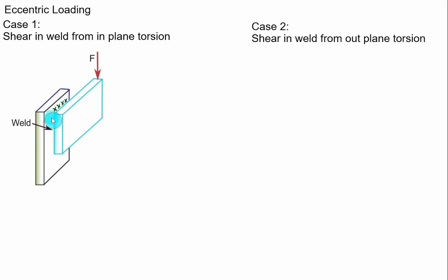Suppose we want to do the welding here also. In that case also, we have the force in the same plane. You can even do the welding from the bottom side also. So any of these cases we have to consider. Either we can have a top weld, or we can have the vertical edge on this side as well as on the back side, or we have full U type of welding. But this time the force F and the plane of weld are in the same plane.